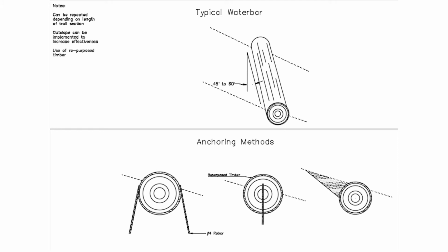At areas 1 and 3, the water bar will be the only alternative used. It was chosen for area 1 because there is no place to properly direct the water off the trail with either the French drain or drainage dip due to the retaining wall that surrounds it. It was chosen for area 3 because it is at the top of the mountain, making it the hardest spot to access. When installing a water bar, no heavy machinery is necessary. It will also be used at typical area 2 along with a drainage dip to decrease the momentum of the water coming down the trail.